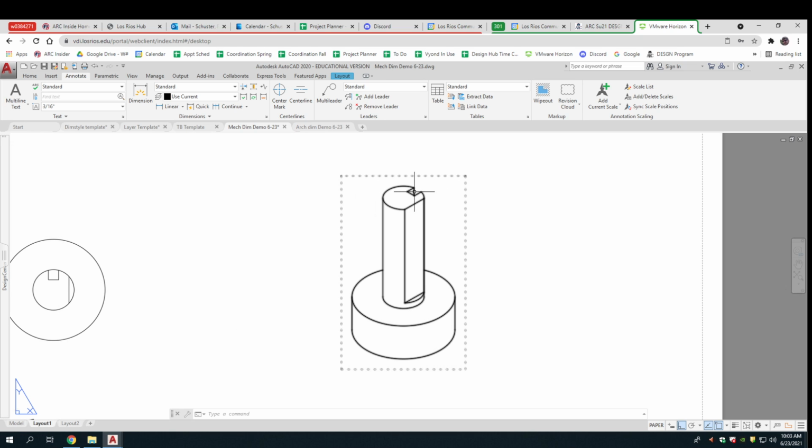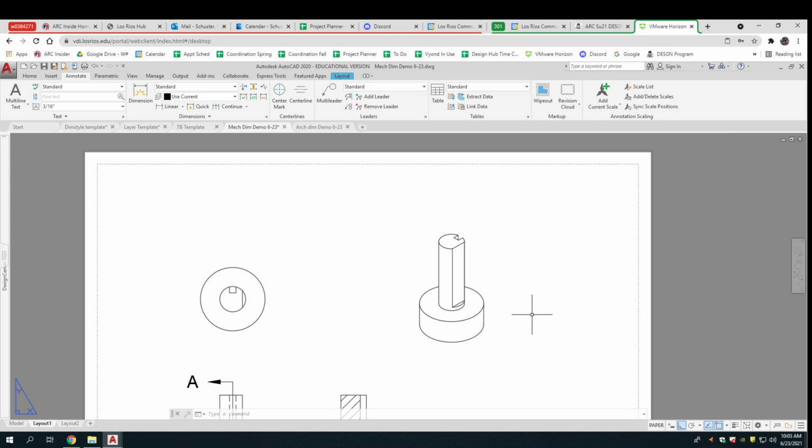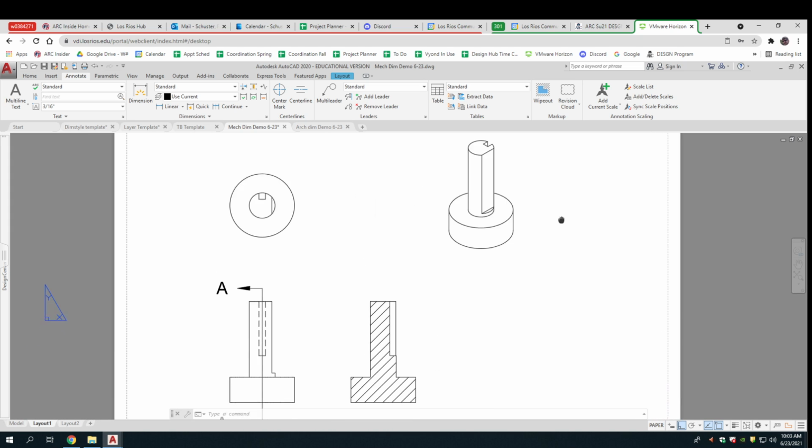There would be a key that would transmit the torque to the outer part. And then sometimes there's a flat on it that you can run a set screw in just to help keep it in place. So this would be, say, a gear or a driver, and then something would slip onto here. So this is a real common little gewgaw.